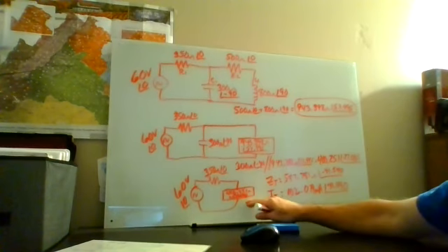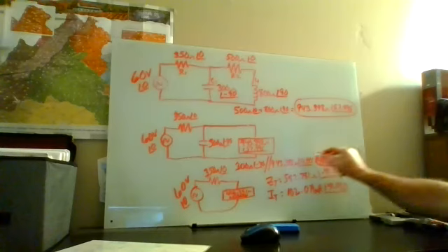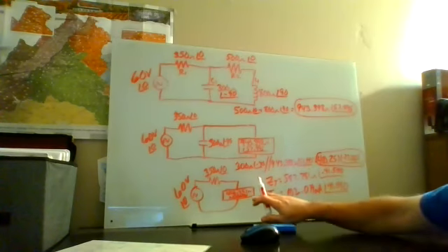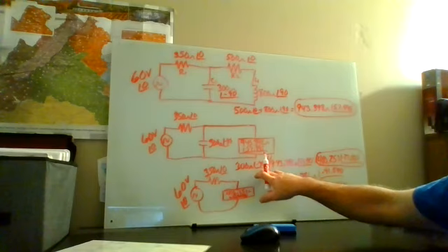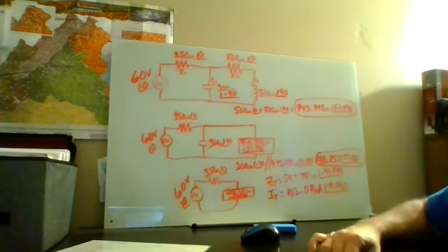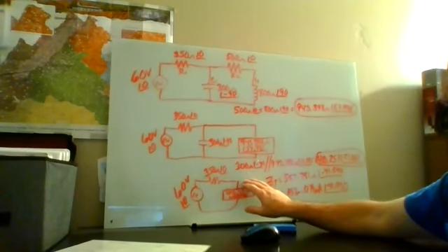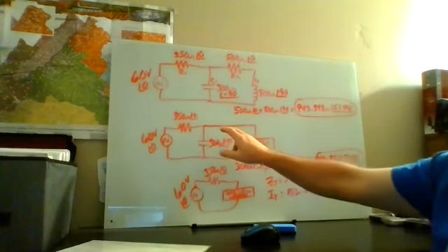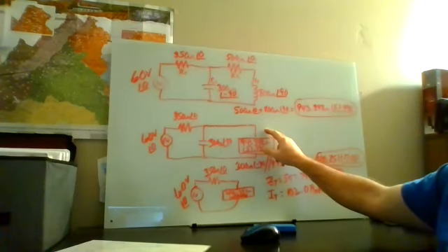So now I got this box. Well, oops, I forgot to circle it. I go back to what I circled. That's how I found the box. How did I find it? These two were in parallel. What's constant in a parallel circuit? Voltage. So I bring the voltage from here, which was 40.834 volts at an angle of negative 35.465. I bring that voltage back to both my capacitor and to this box.